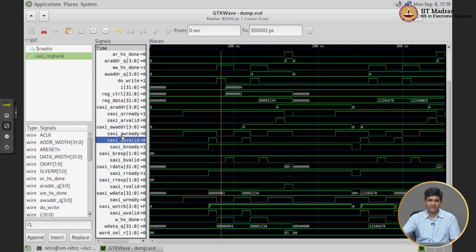Okay, so to summarize, the point of this exercise was first of all to recap how memory mapped IO works, how we can implement something like that in a simple Verilog code corresponding to a register bank, and how using Cocotb over here helps us to very easily simulate the fairly complex AXI protocol and test different kinds of functionality with it.